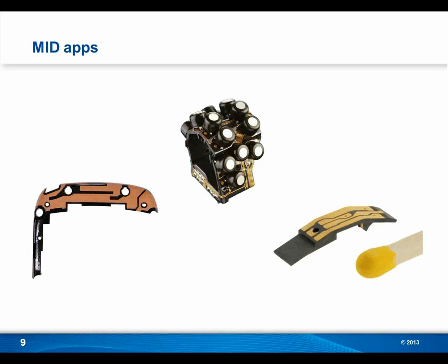Yeah, thanks, Shane. I think the most important factor on an MID is that we really get out of this two-dimensional world that we're all used to, in terms of regular circuit boards, or flex circuits, even those start their life as a two-dimensional item, and really start to think three-dimensional. That allows for much higher integration of functionality. And if you think of items that are constrained in space, or where we want a human-machine interface that is not always two-dimensional, the MIDs can be very beneficial there.